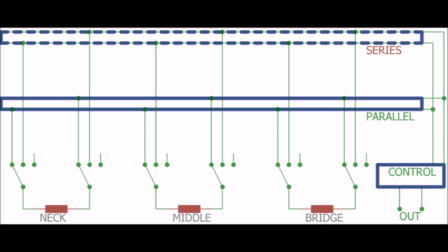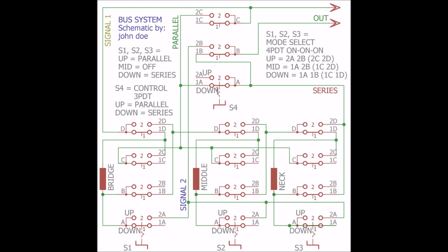In the circuit diagrams, I decided to use an expanded rendering of the 4 PDT switches, and the 3 PDT switch, into individual component SPST switches, to make it easier to follow the paths and switch operations. The switch schematic diagram used is actually a representation of a slide switch, or a rotary switch. The pickup switches perform only simple binary operations, connecting or disconnecting pickup leads to the buses. The circuit buses are labeled for convenience, and a simple trace will reveal how they function.